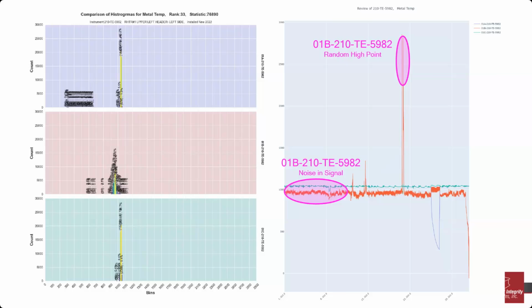Do you also have monitoring on the cold reheat or the hot reheat bypass? No, I'm sorry, I'm reading the question wrong. Yeah, Nick, this is on the HP bypass to the cold reheat, this case study that we're talking about now. And he asked, is there a drain pot on that pipe? And I think the answer is probably no.